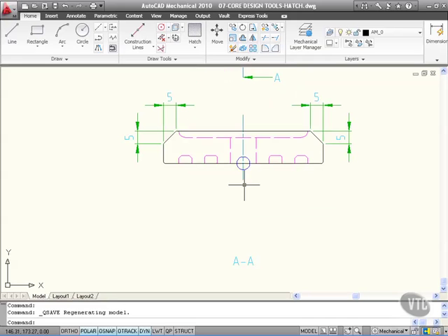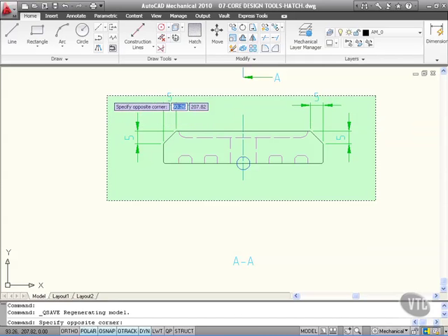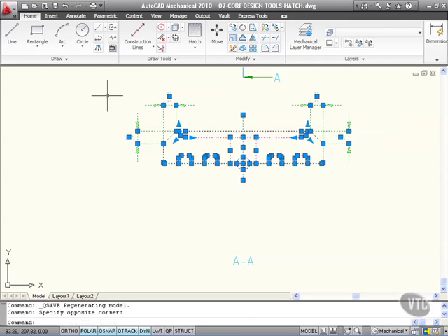So zooming in again, what I'm going to do now is select the geometry that I want to copy. So let's do that first. Select everything by doing a crossing selection. So left click there, drag up this way. Doesn't matter if you cut through those dimensions, and left click up here somewhere. Everything gets selected. Now dimension wise, you don't want the dimensions to come down onto the sectional view. So holding down the shift key, click on each dimension, and you'll see that they deselect from the selection set. Don't click on the grips, that'll obviously take you into grip edit mode. So what you need to do is select on some lines there that form part of the dimensions.